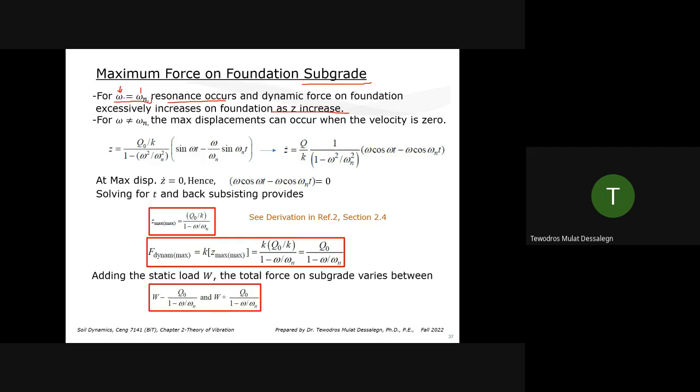That's why we try to predict earthquakes. We know the system frequencies around the structure. We know what the soil character is. We do borehole tests, geophysical propagation tests, anything, trying to understand what the soil natural frequency is. And we design our structure so that the soil frequency is at least different from the structure frequency. We don't want them to coincide. If an earthquake comes and they coincide, then that's total collapse. So we try to avoid it.